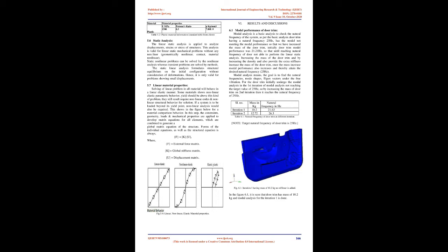2. Modeling parts with a complex geometry involves the usage of specialized software to achieve a virtual model. From the equivalent stress distribution of an analyzed component, it can be seen that these areas have high levels on the fixing areas to a metal structure. The displacements of the lignocellulose material door trim panel obtained by FEM are smaller by 43% than those of the polypropylene panel. The small displacement values for the lignocellulose composite component are due to its high rigidity and low weight, given the lower thickness of the material layer of the panel. These are gradually decreasing from 1.81 kg to 1.49 kg.